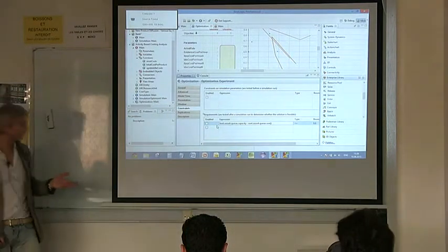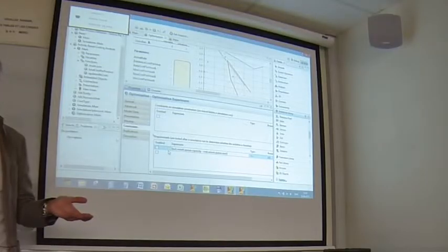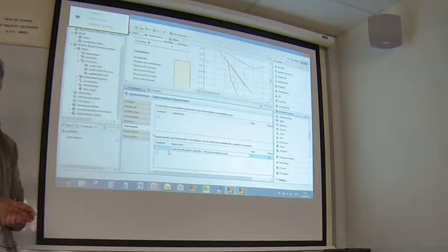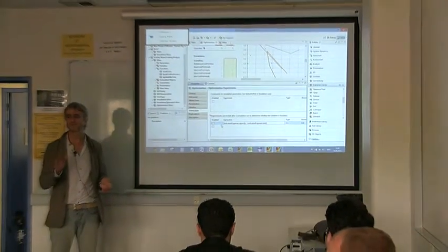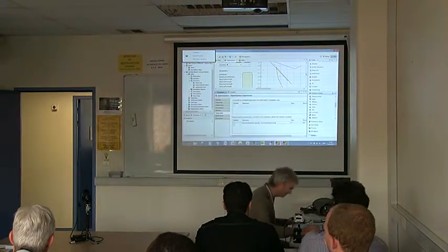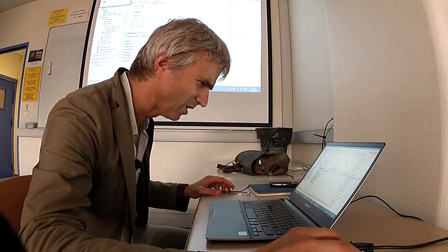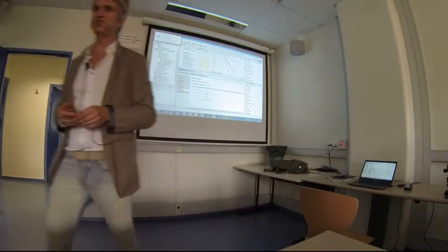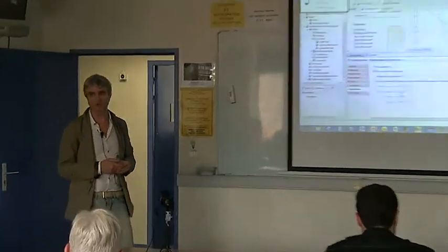Okay, guys, I think we're finished for the first part, and I can answer 2 short questions at this time. Could you please click on replications? Yes, if you have random variables in the model, if your model is stochastic and you're optimizing under uncertainty, then of course you have to use replications, and this is the interface for defining the number of replications.